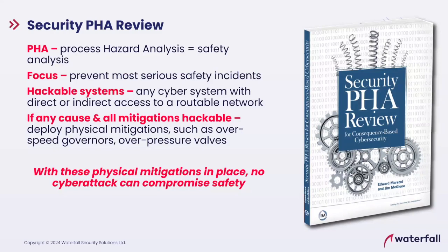And if all of your mitigations are also hackable, if all of your mitigations can be compromised, now we've got a problem. We've got a cyber attack that can cause the event, and the cyber attack could also compromise all of the mechanisms that prevent the event. Now we've got to do major cybersecurity. We're talking SL4 grade cybersecurity. These are expensive. This is the most expensive version of 62443-3-3.